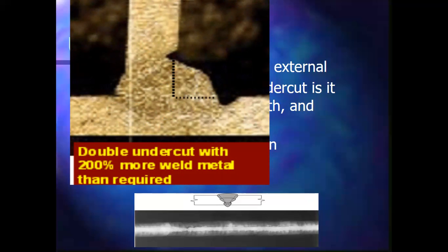should be filled in. So if we were to apply a bunch of stress here, or we had some stress coming through here, first it would hit this notch and it'd probably start cracking there. It would travel through, hit this, and this probably crack there. So there's a chance this could crack right through to here. That could shear off. This could crack through down to there. That could break off. Basically, this is all sorts of bad.